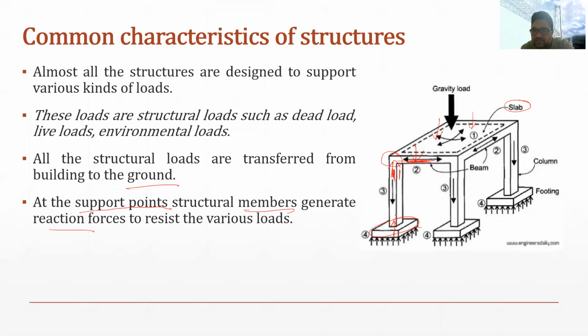Similarly, the load is transferred to the foundation, and the foundation is resting on the soil. So the soil will also offer a reaction. You can see these small arrows; they are actually showing the reaction offered by the soil. So that is the thing that happens when the load is transferred from one element to another element.